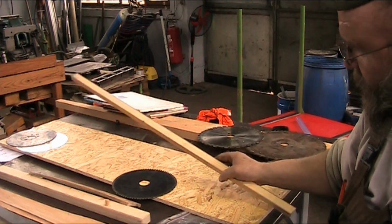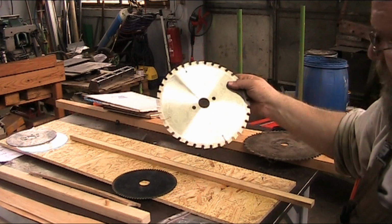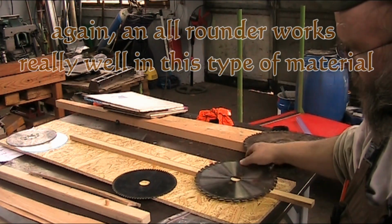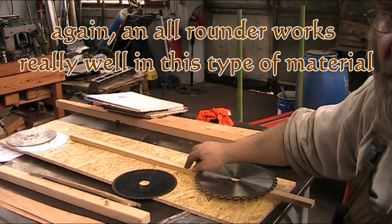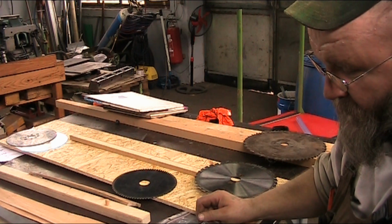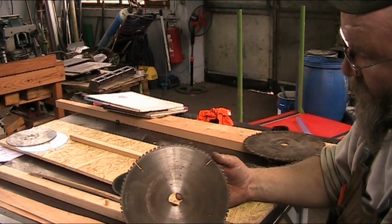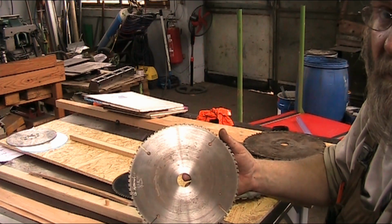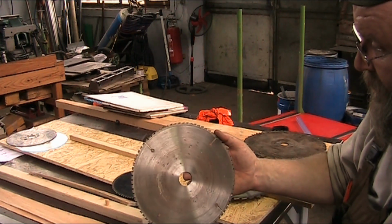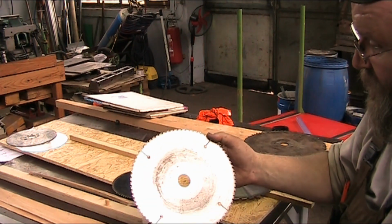So this is a material that you can cut with this kind of blade, although I don't recommend it because you'll see burning on the face of the wood. The MDF part will be okay. You'll need a different type of saw blade, more along the lines of this. I don't have a coarser tooth blade than this, unfortunately, right now at hand. So I'm using this little guy here.